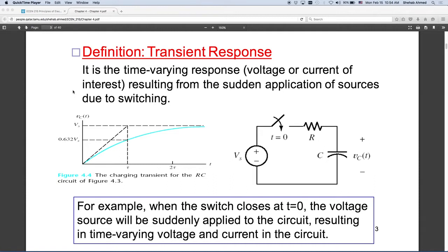It also helps when you're talking about power conditioning circuits. If you want to change a voltage from one level to another, you use lots of inductors and capacitors to do that. So you charge a capacitor to a certain voltage, charge a second capacitor to a certain voltage, for example. So now you have two capacitors, and maybe you can double the voltage at the output by putting these two capacitors in series, right?